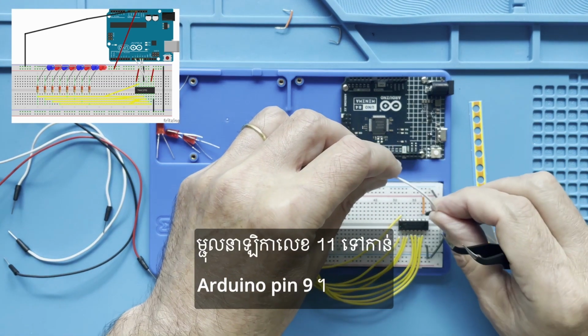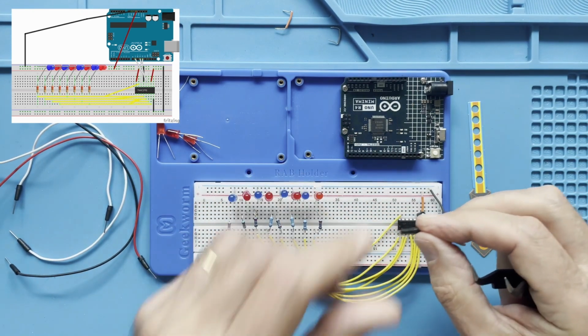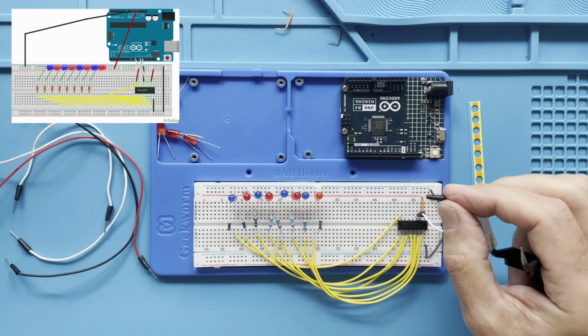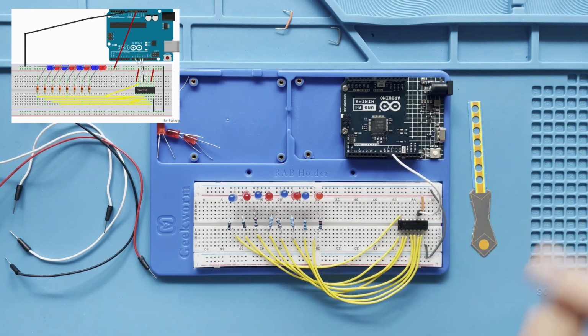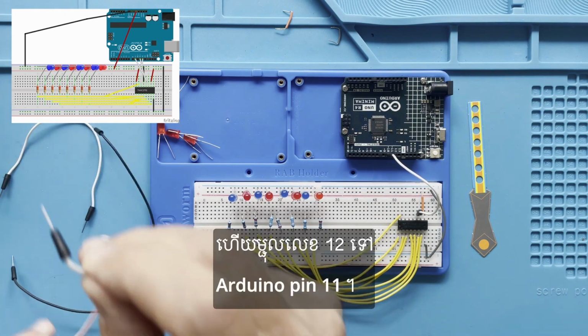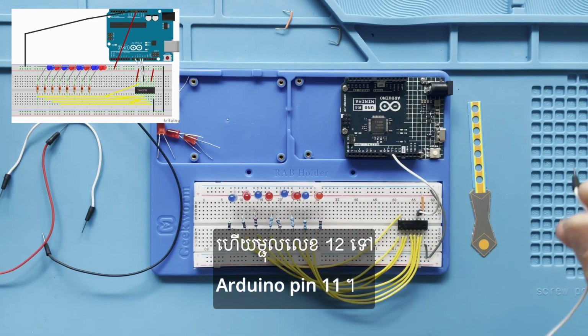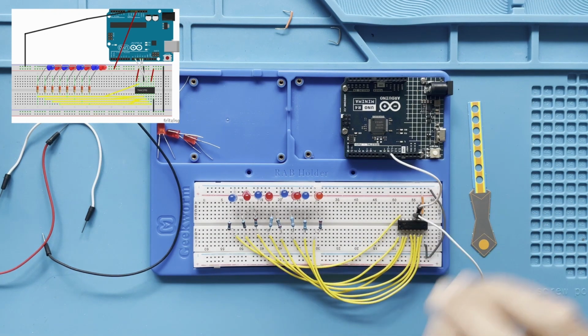The clock pin number 11 goes to the Arduino pin 9, and the latch pin number 12 goes to the Arduino pin 11.